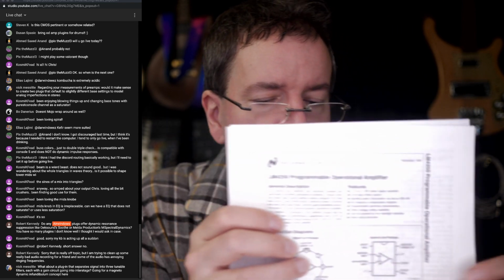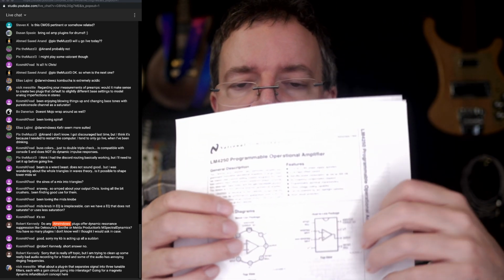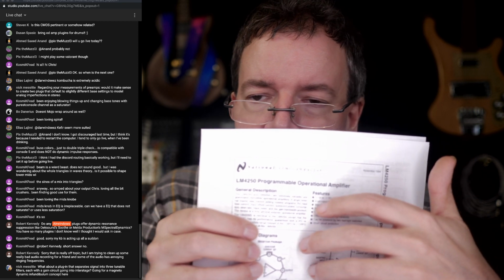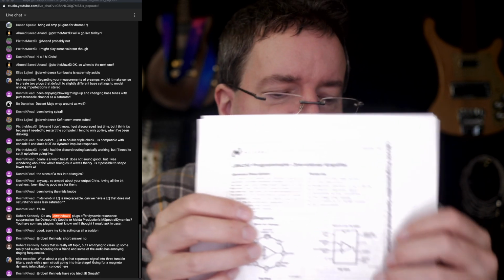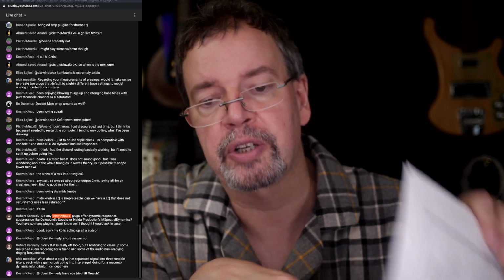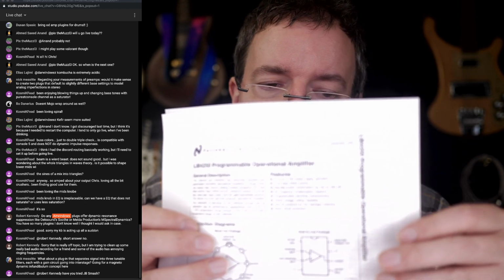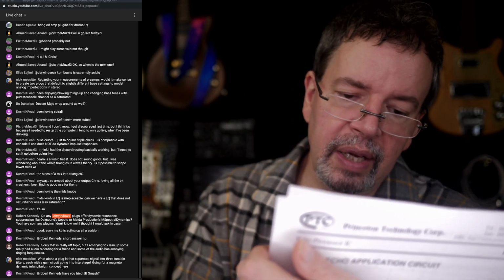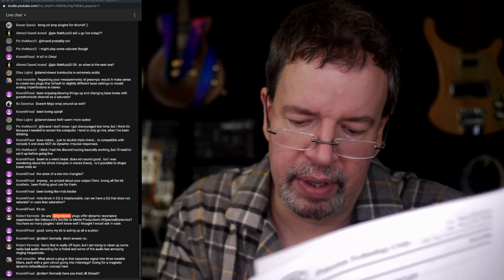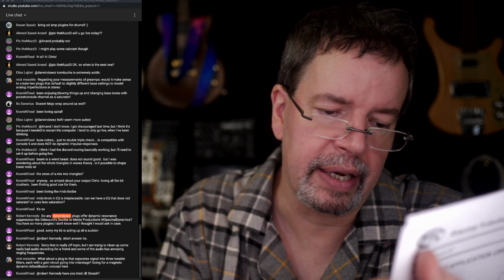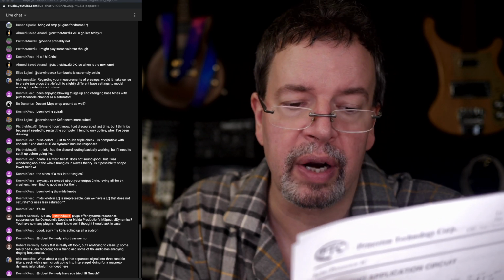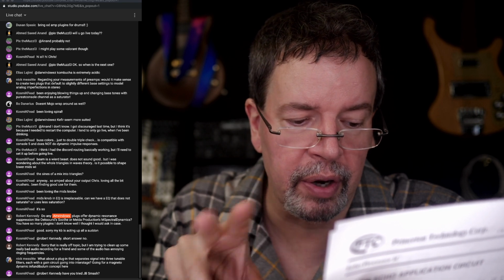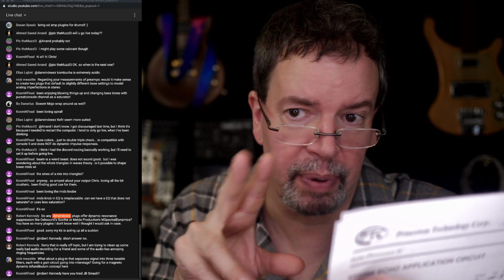It can be very efficient as far as power consumption is concerned. But what you do basically is use this as a dirty, nasty op-amp. And it gives you the sound of sort of those special op-amps in old Japanese stomp box circuits, where it'll color the sound of a guitar or whatever, because it's slowing the slew rate, because you can run it on the micro power so that it can't pump out lots of slew rate.